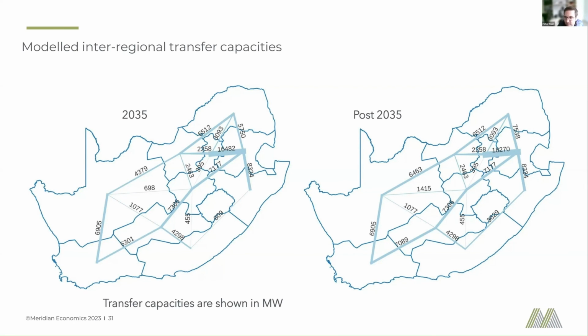I must say we don't include operating reserves at the moment in the capacity expansion model. We've kind of subsumed that into the planned reserve margin, which is typically on the higher side of that reserve. But in the dispatch model, there's more detail around spinning and non-spinning reserves. And for example, there's some interesting work that you can do around minimum levels of inertia in different regions. Those kind of things you can start to play with custom constraints.